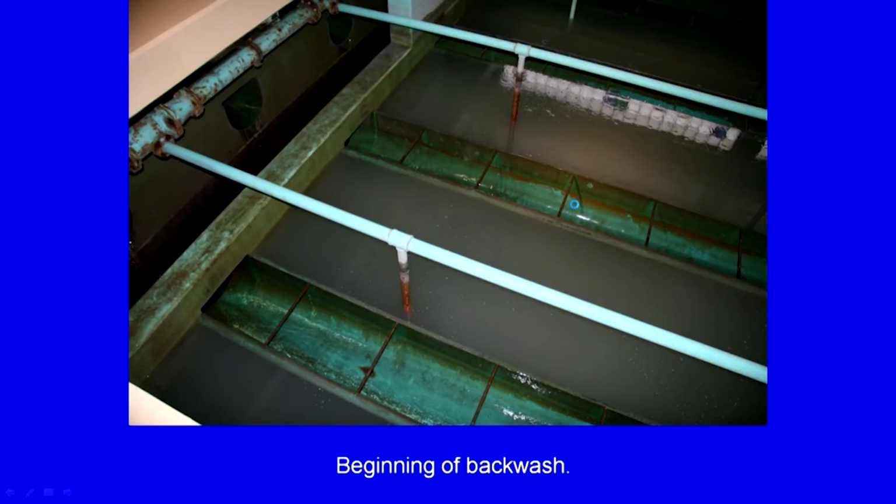Let us move on. So, what do we see here? Here they are going to begin backwashing. These are the backwash troughs. They are just about to start backwashing, and this is where the filtration was occurring, but they have just started pumping water in the reverse direction. So, water is going to come out from here and be collected in these backwash troughs.